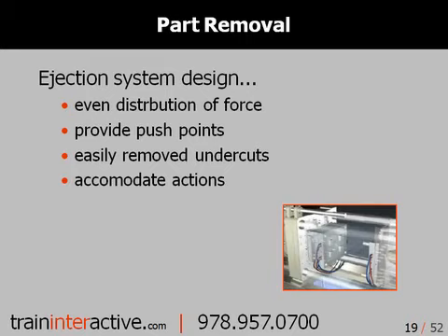When you have to deal with undercuts, be sure to position them in a manner which will best facilitate their removal during mold operation or part ejection. You must also allow enough space around the undercut for actions such as lifters and slides to properly move.